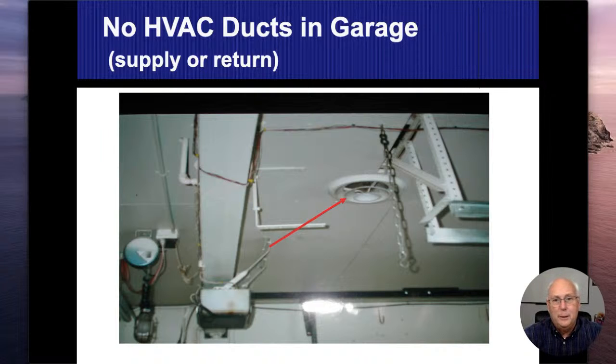All right. Here they ran some ductwork through the garage, and they actually have a diffuser up in the ceiling of the garage. Sounds great. Now I got a heated garage, so everything's good. But we're going to talk about this, if I do an exterior one, which I think I will. We're going to end up talking about breaching of the firewall. So if I have an opening with ductwork that comes back into the house, if there's any gas fumes coming from the garage, or God forbid there's a fire, that just makes it an easy way coming in there.